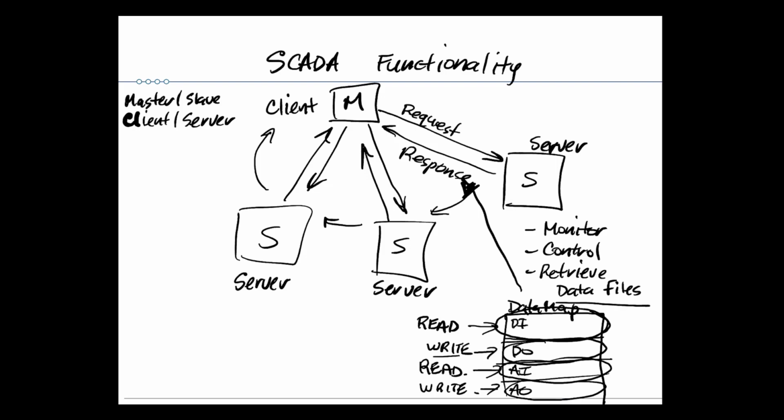What is the value in that register? Because if the breaker didn't trip, where's the problem? Is the problem in the actual writing of the register or in the field equipment? And so we always want to have the functionality to actually read an output data type as well for confirmations, right? So we would have a read functionality here as well, and a read functionality here. So what it means is that when we write it, we also will be able to read it. And so for output data types, we're looking at read-write functionality. For input data types, we're looking at read functionality.